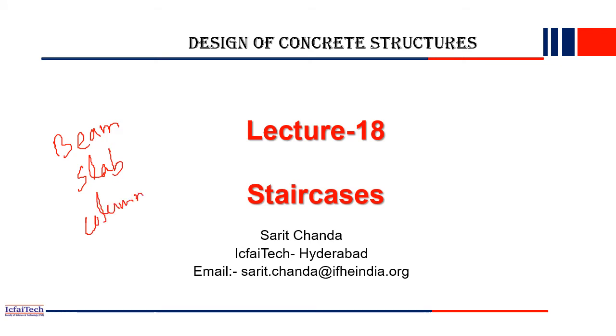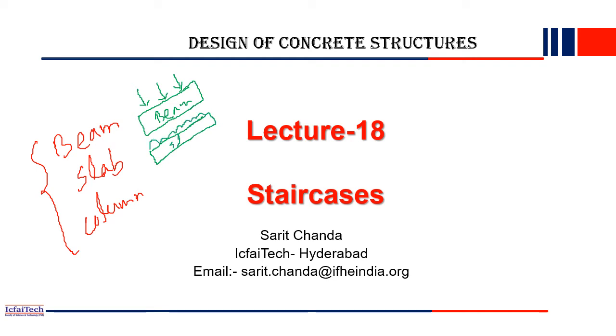What is the major difference in all the structural components we have designed till now? A beam is a member where the loads are acting in a transverse direction. Any structural member where the loads are acting in a transverse direction will follow beam design. Now, if a structural member is very thin and moderate amounts of loads are acting on it, then how do we design it? That comes to be slab design. And if a structural member is subjected to an axial compression force, then the design of that element will follow column design.